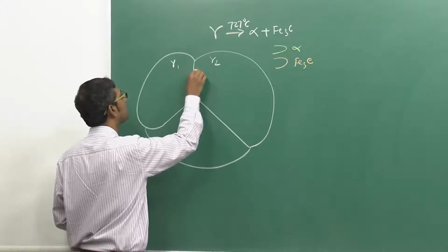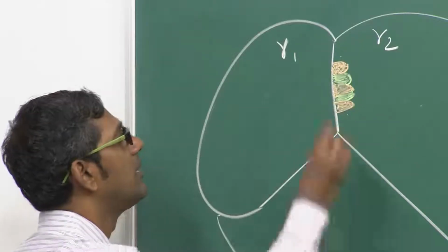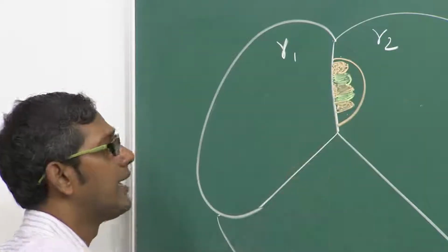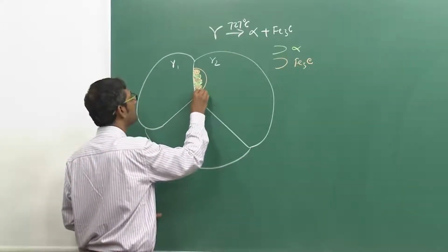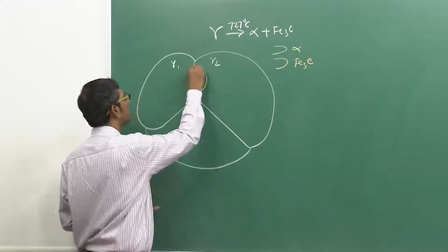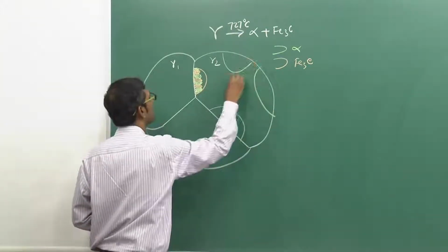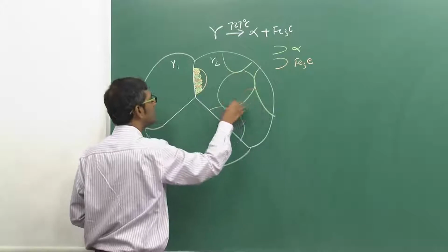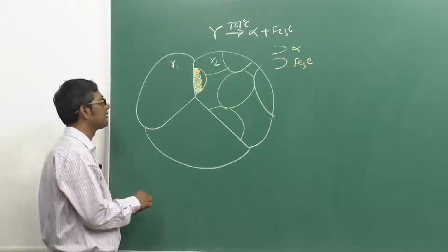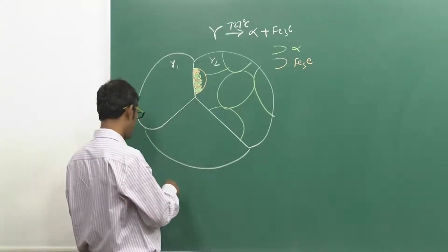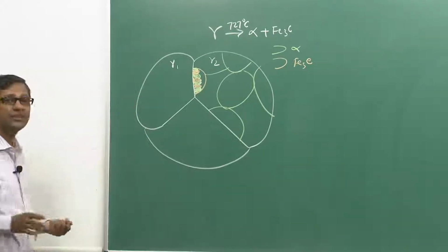This is similar to eutectic transformation from the liquid. Exactly similar thing happens when lamellar eutectic forms. So, this will lead to a colony, and this colony will slowly grow into the gamma grain, and these colonies will appear in many places, here or there or there, and that is what you have seen in the microstructure. These are the grains of the pearlite. Remember, each of these actually consists of both the phases, cementite and alpha. So, that is the way transformation happens.